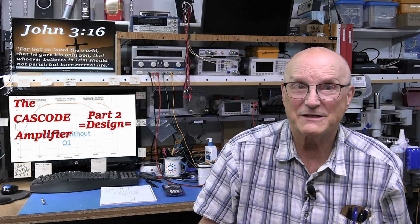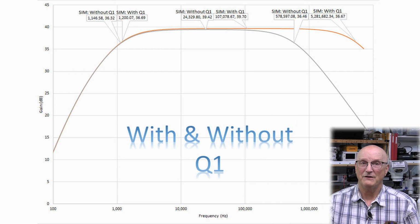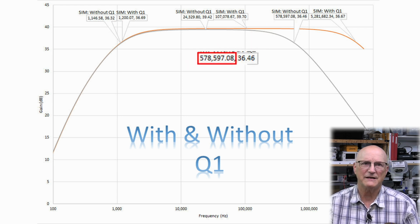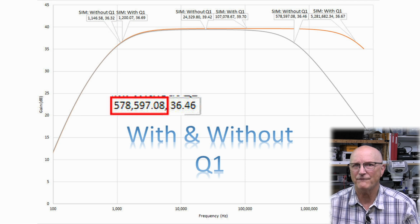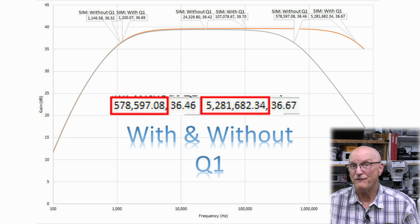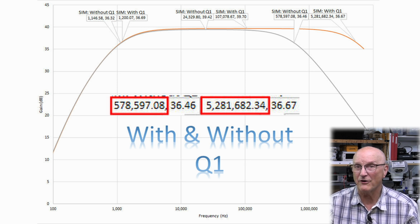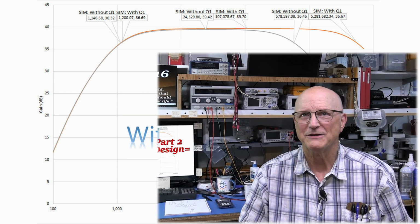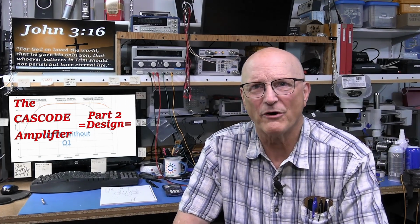So what are the simulation results? Well, here are the frequency response results of both versions laid side by side. Notice that the minus 3 dB drop-off for the plain common emitter amplifier sits at 579 kilohertz. The CASCODE amplifier's high-end response is at 5.281 megahertz, and well, that's almost 9 times greater than the plain common emitter circuit. Okay, so what about the breadboard results?